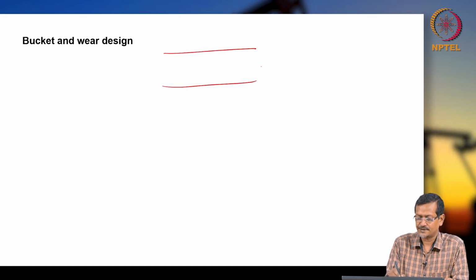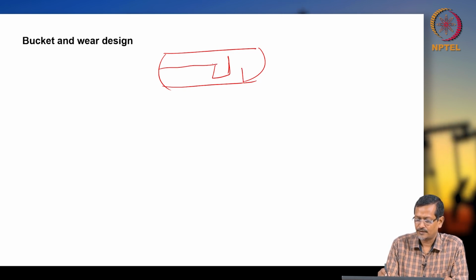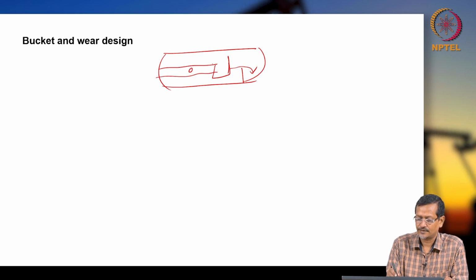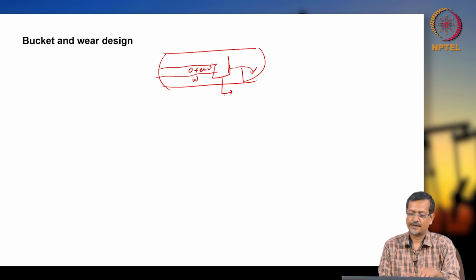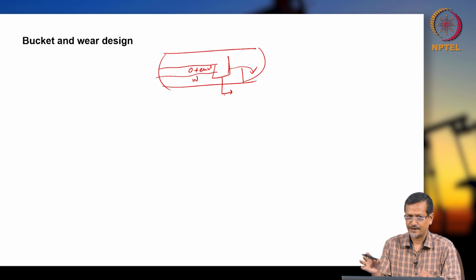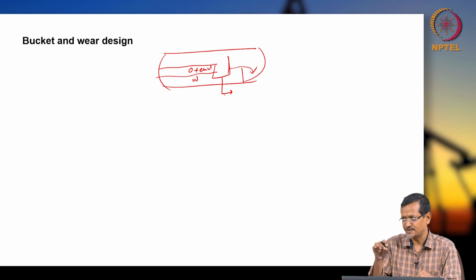Okay, we already explained the bucket weir design. Bucket weir design means you have one separator, you are creating one small bucket, one leg longer, and you are creating another weir, and you are getting fluid flow here like this. Okay, oil, water, oil plus emulsion. In the next stage, oil and emulsion, when you are getting them, you will be separating oil and water separately, and will be treating emulsion separately.